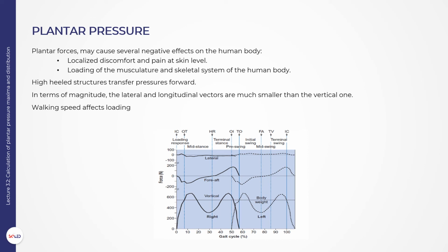Walking speed affects loading. A higher pace increases the overall load. When running, these loads can be up to 3 times the weight of the human subject. Pain thresholds can be as low as 160 kPa for certain parts of the plantar foot surface. Practical experience shows that any values exceeding 80 kPa in static standing regimes are significant and shall be avoided, through improved sole geometry and selection of materials.